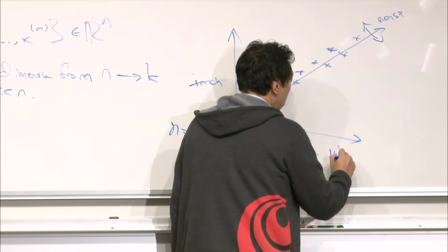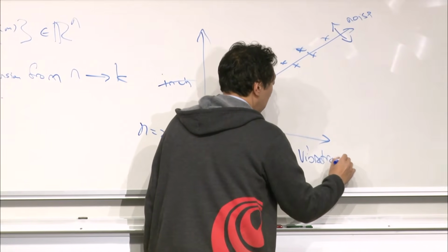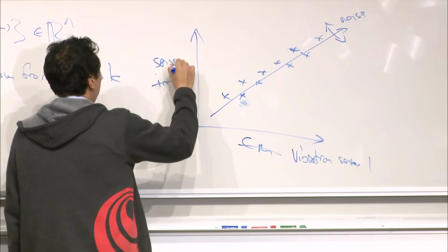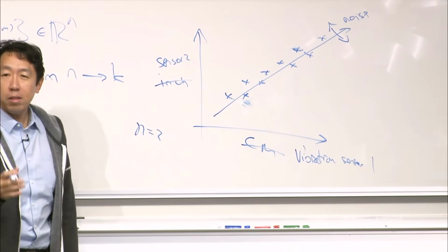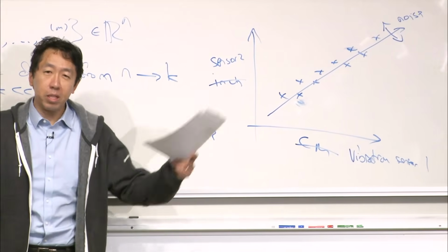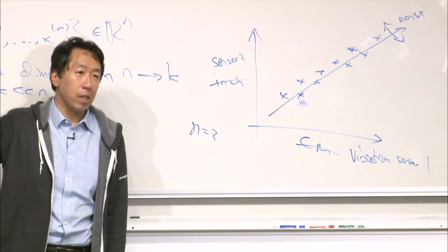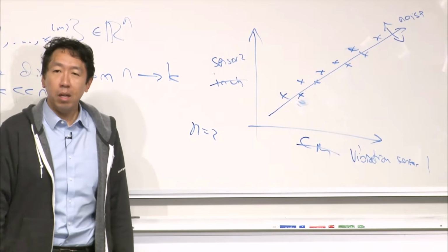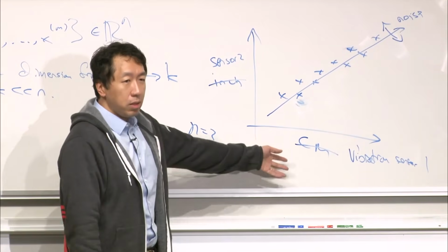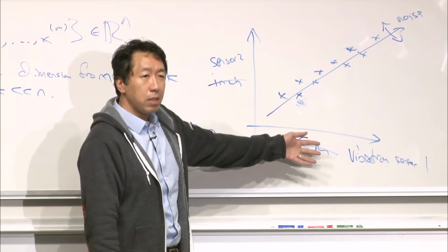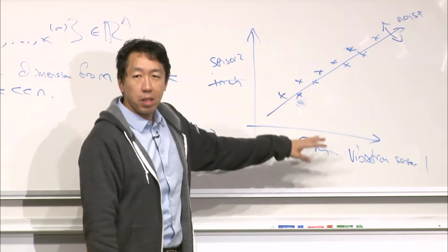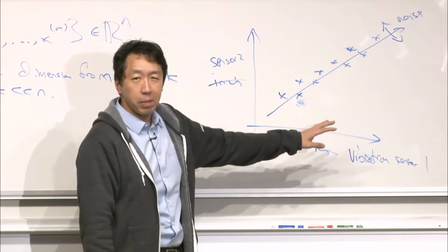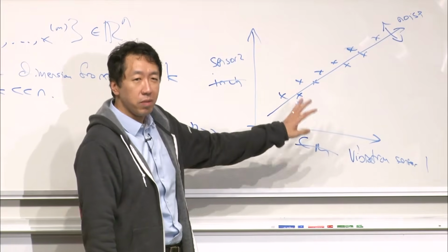So you can have a vibration sensor 1 and a different sensor 2 on big factory machinery that's shaking, right? And you could have two sensors, maybe made by two different manufacturers on two different parts of the machine. And again, the noise may be bigger, but maybe you think, well, both of these sensors are just measuring how much this machine is shaking, because you want to do preventive maintenance.